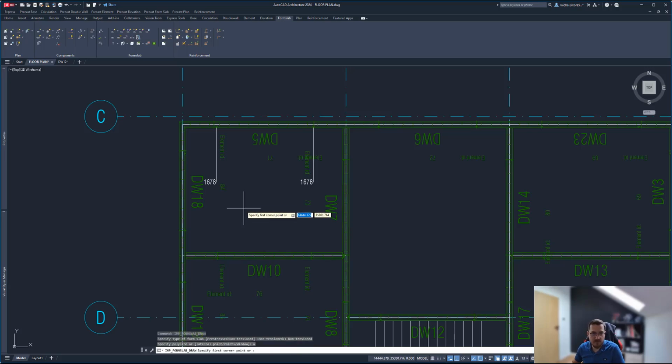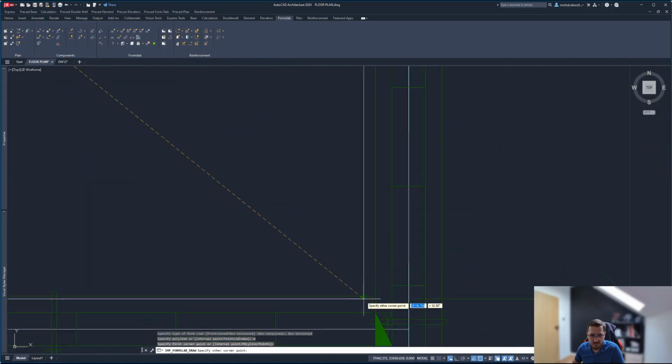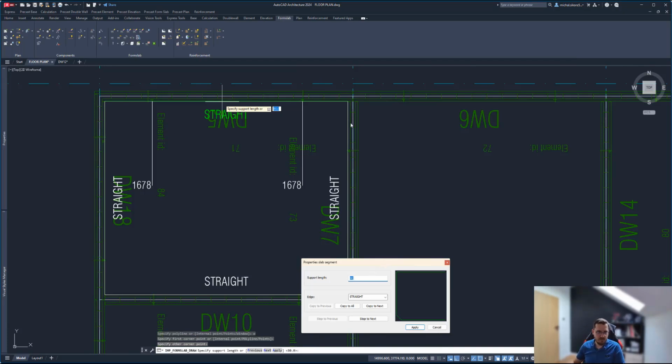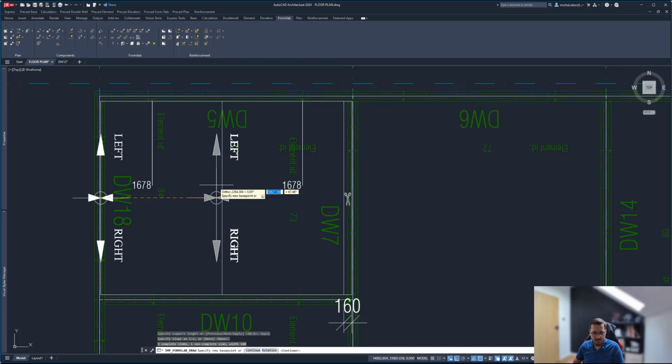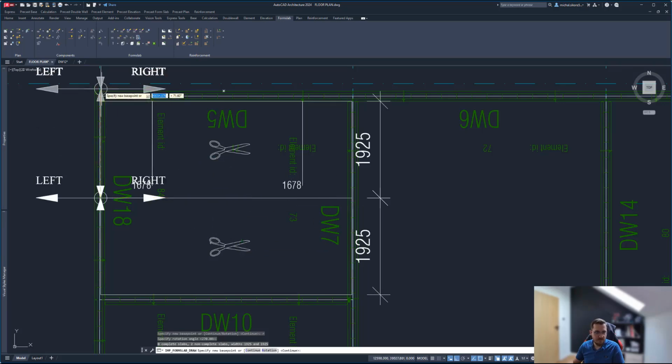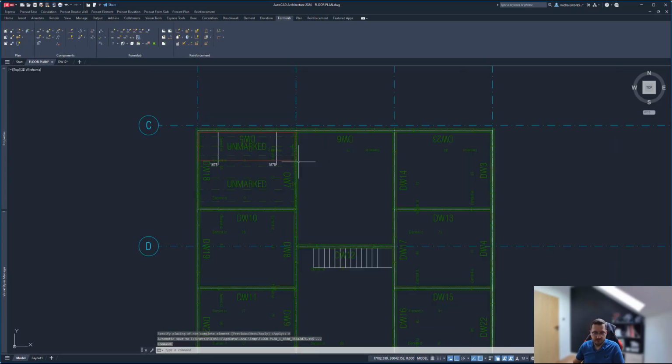What I'm going to do is place the slabs by the window. I'm just going to select that and go ahead and do it this way. I'm going to do a support edge, not here, but on the other direction. So step to next. So this is going to be my support edge. This next one is going to be 0, and this one is going to be 80, like that. No slope, and let's actually rotate that by 90 degrees. And that's that. And let me choose the start point like that, and this slab will be the cut one. I'm going to apply this, and this is my placement.